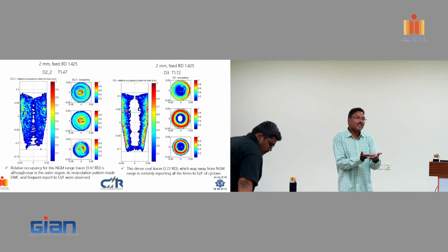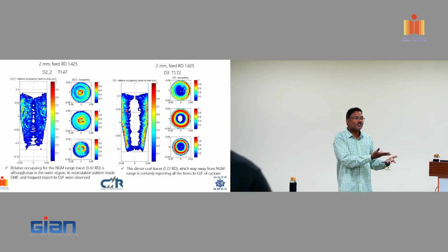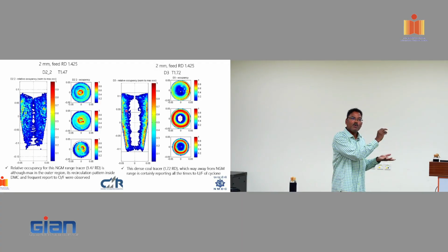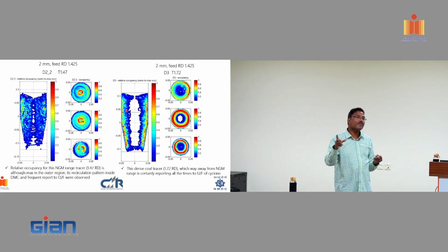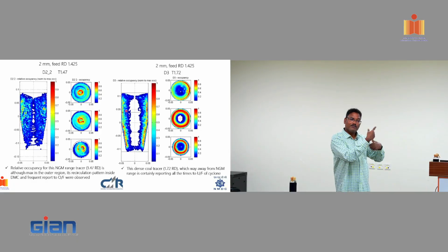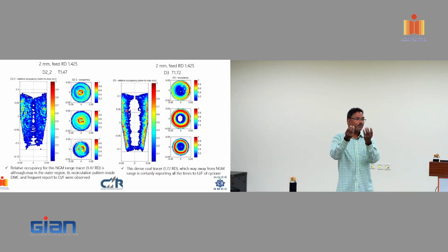So then essentially it becomes multi-component. Shells are made of the calcium-rich mineral, whose density is much lower than 2.7, 2.8. And then you have other materials that might have a different density. So essentially it's a subject of multi-component separation. And they also attempted one multi-component study for jigging. Basically, instead of grinding everything, we can try to get the maximum possibility of these diamond grains coming out if we use this pulsation-based method. That is the operation called jigging.